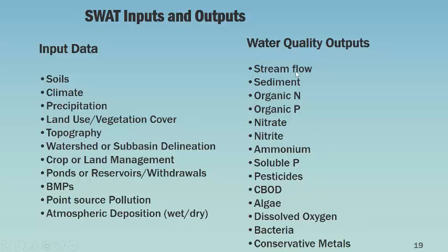It shows you all the different outputs that you can get. All the outputs you can get at 3 spatial scales, either at the HRU level, that means the individual field or farm level, or a parcel level. You can also get at the sub-basin level, which is a group of HRUs that belong to that particular sub-basin. And then you can also get the river process actually. Anywhere along the river, any point along the river, you can get model output. So some of the output that you can get is what's shown on the right-hand side.